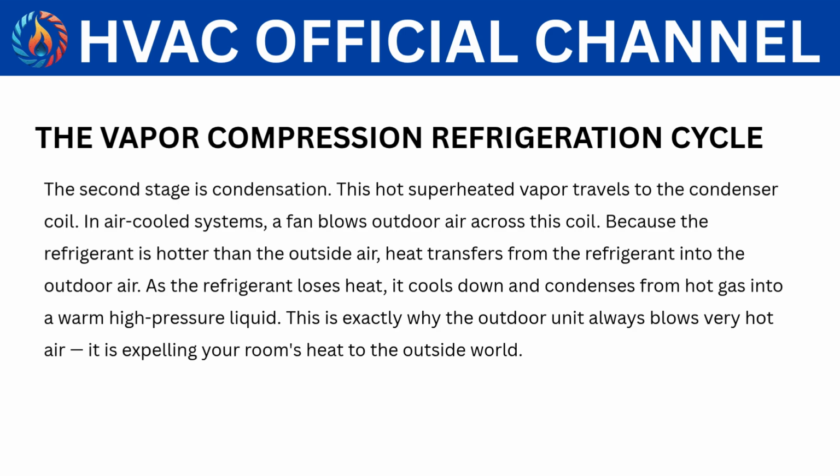Because the refrigerant is hotter than the outside air, heat transfers from the refrigerant into the outdoor air. As the refrigerant loses heat, it cools down and condenses from hot gas into a warm, high-pressure liquid. This is exactly why the outdoor unit always blows very hot air. It is expelling your room's heat to the outside world.